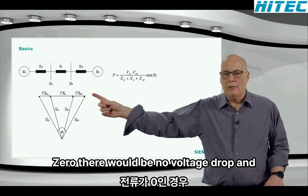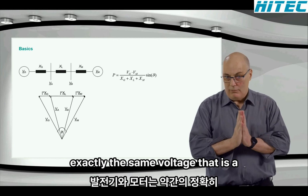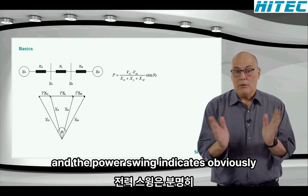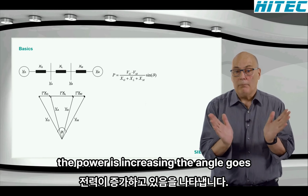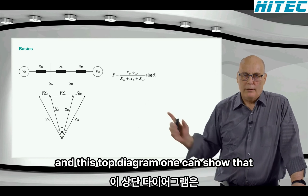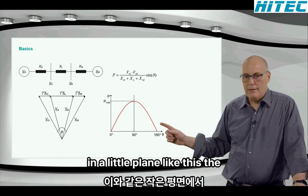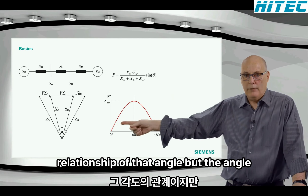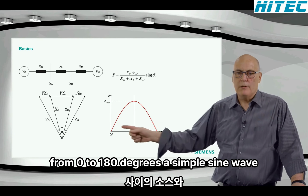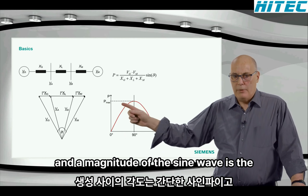If the current was zero, there would be no voltage drop, and the generator and the motor would have exactly the same voltage. And as a power swing indicates, if the power is increasing, the angle goes up and down between the generator and the motor. This top diagram can show the relationship of that angle, between the source and the generation, from 0 to 180 degrees, as a simple sine wave. The magnitude of the sine wave is the P max.